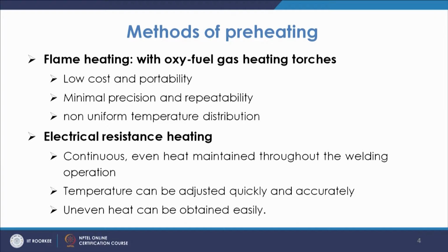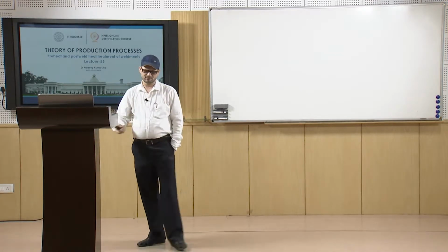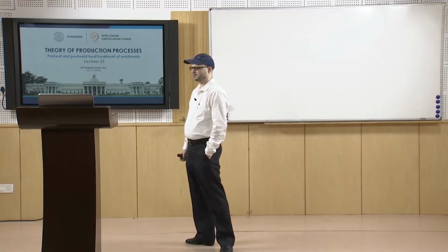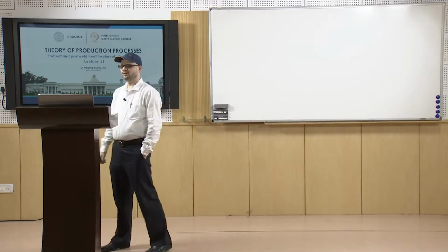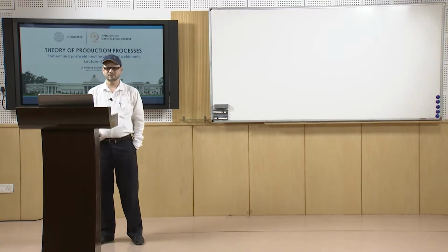But the disadvantages are that you have minimum precision and repeatability, because it is normally done manually. Precision is also less because the flame has spread. Then you have a non-uniform temperature distribution also. So, that is the disadvantage.